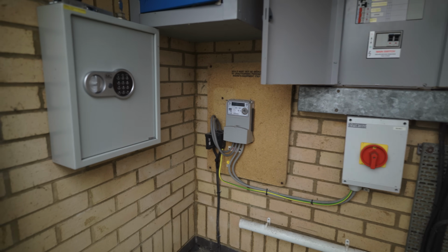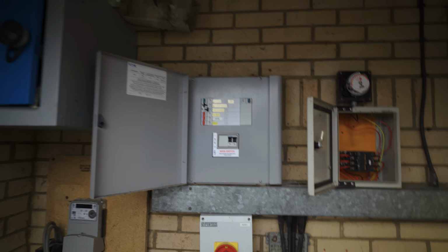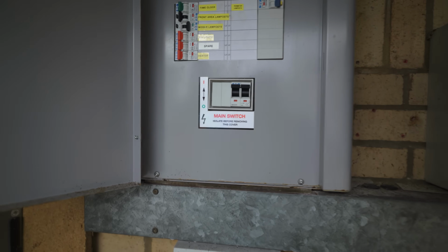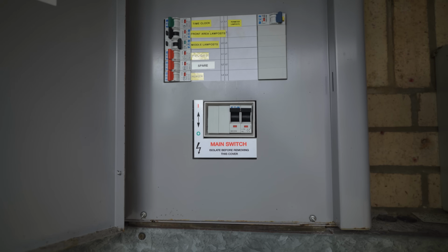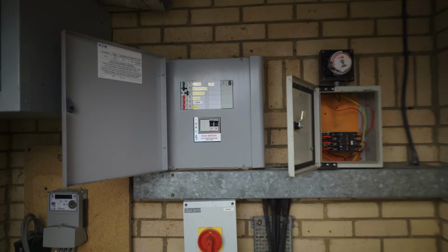We've just got a nice little single phase supply in here, 100 amp 1361 meter isolator, and then 3-phase board. Must have a single phase, well, it's got a single phase switch in it. Must have a linking kit or something in there. But we'll get the cover off anyway. We'll take a closer look at this.